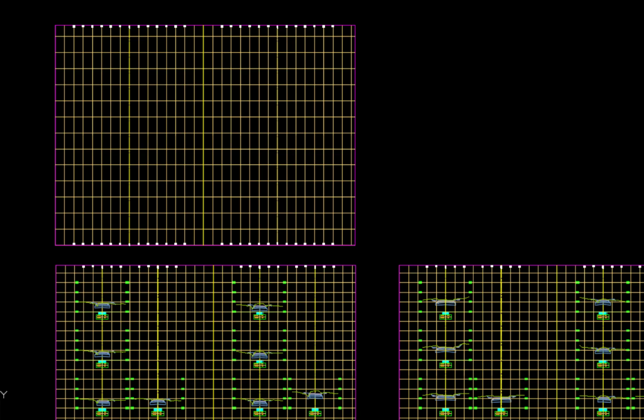cross-section sheets, similar to the procedures previously used for plotting road sections. For this video, a pre-formatted grid sheet having a horizontal scale of 1 inch equals 15 feet and a vertical scale of 1 inch equals 3 feet will be used for the driveway profiles. This will allow 2 columns of profiles having a swath width of 90 feet on each side of the road center line to be plotted on one sheet, with each column containing 6 driveway profiles.